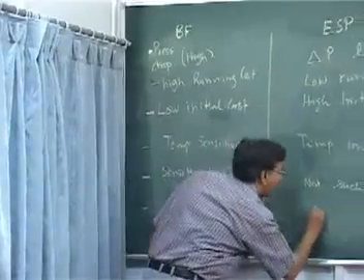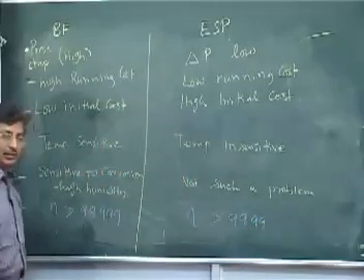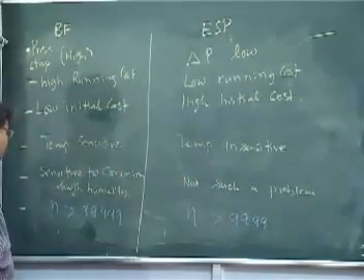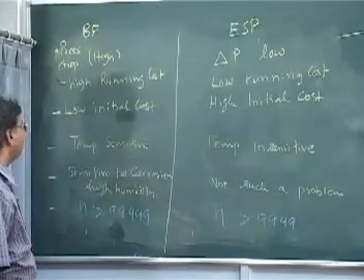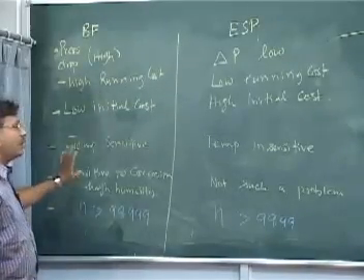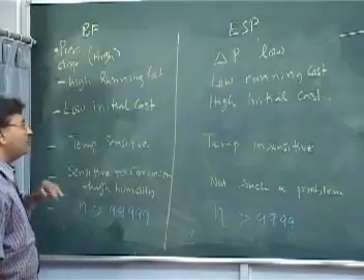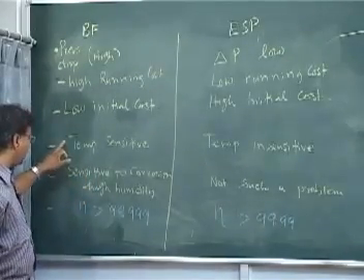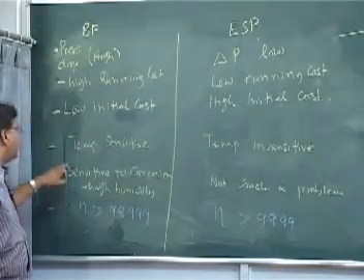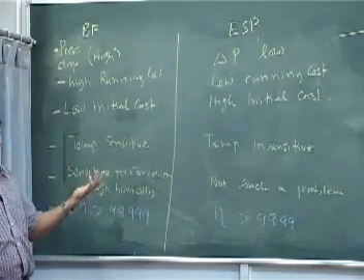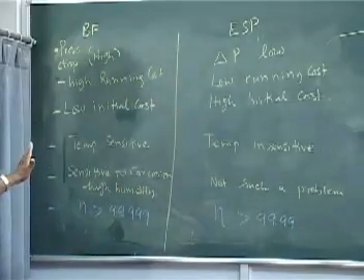Efficiency here is also high, of the order of about 99%. So they are both comparable, but depending on what situation you are in, you have to choose. The fabric filter is temperature sensitive, and sensitive to corrosion and high humidity. So people use different kinds of fabric filter. For example, if you use Teflon, what is the problem with the temperature? Depending on where you are, these bag filters are used.